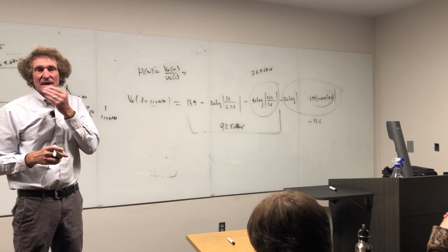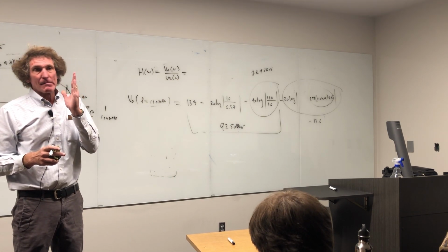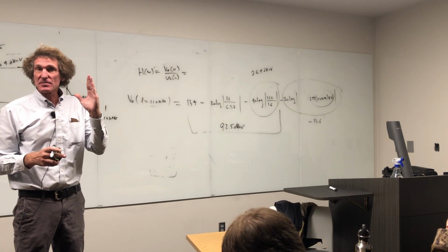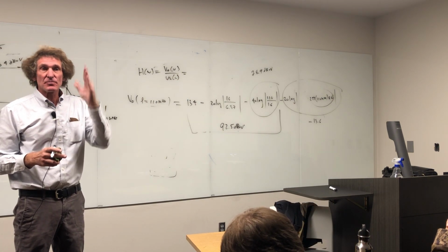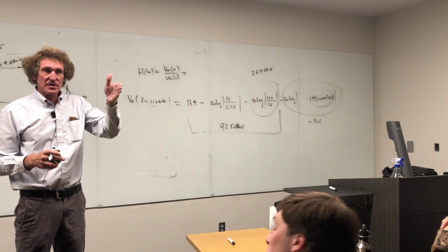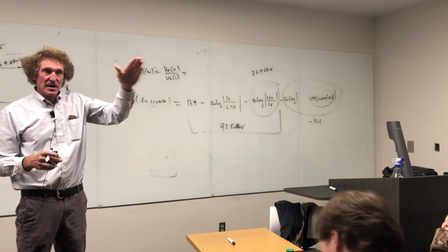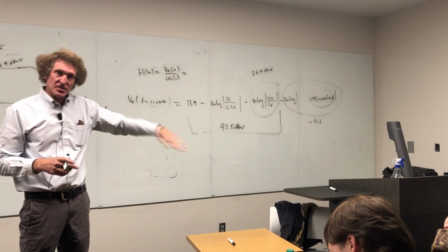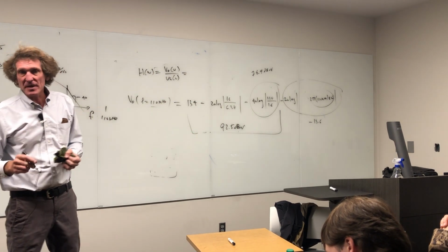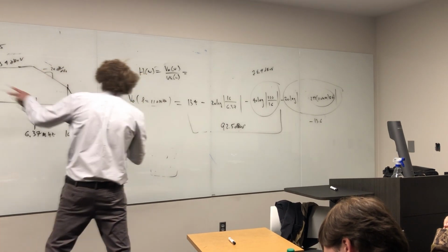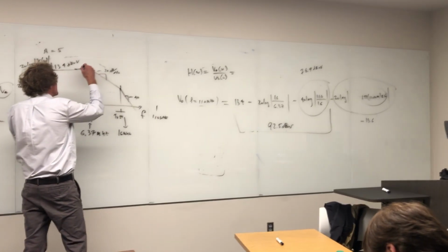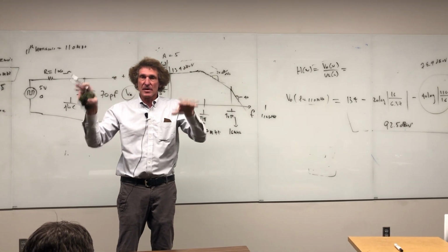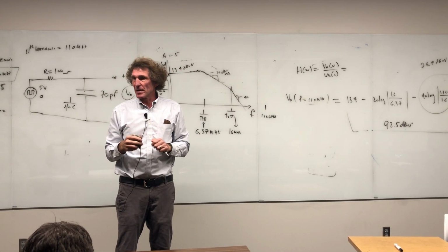And by the way, when you get to high frequencies, at that point where there's an 11th harmonic, 12th harmonic, if you look on the spectrum analyzer, you don't see discrete lines. Theoretically you would have discrete lines, but you don't see that. It's a continuum. This is what you'd actually see in the spectrum analyzer, more or less a curve like this. You won't see just this shape. There'll be noise, bouncing around all the time, going up and down a little bit.